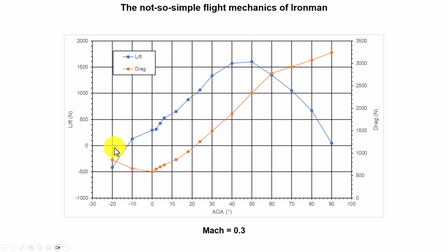So just putting everything in a graphic here, we have the famous polars. Angle of attack, and then drag, lift, now to my left, lift, drag forces, and we plot it here, and we have our behavior. It's nothing to say, I hope you're familiar with aerodynamics. As you keep increasing the angle of attack, lift is still increasing, in this case Mach 0.3. It's a really bad condition actually. Look at that, you need to go to 40 degrees to generate the necessary force. So this is basically not what we see in the movies.